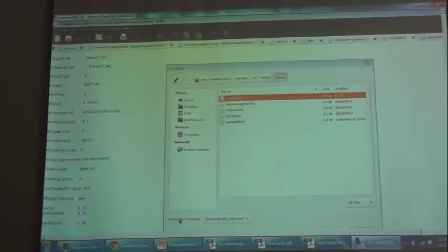But is there some option like this in Fluent? When you do interface tracking, no, there is only one Courant number used. I'm also looking at this for the first time, alpha Courant number. Even in two-phase you can specify it. Yeah, I have to look into it. I've never used it. Probably this is the criterion. Can you just comment this out and run the case once? This one? Yeah. I just want to see if it's a default or if you need to specify it. Maximum. Yeah.